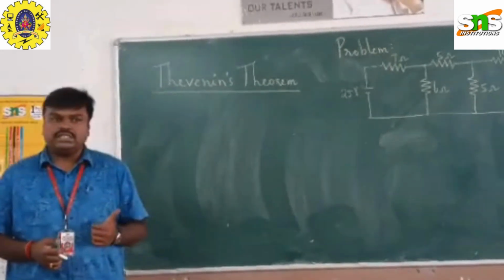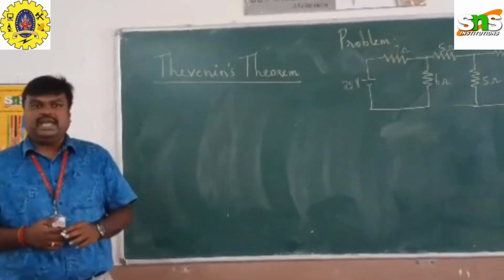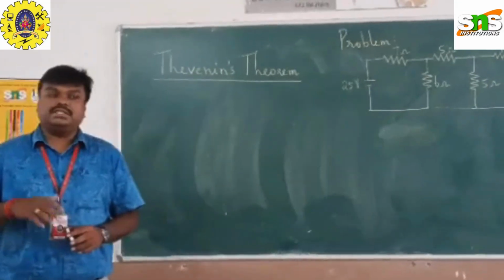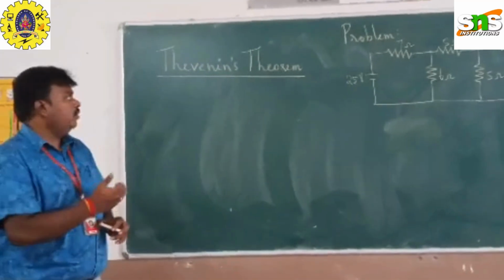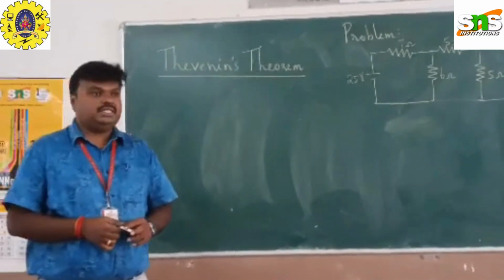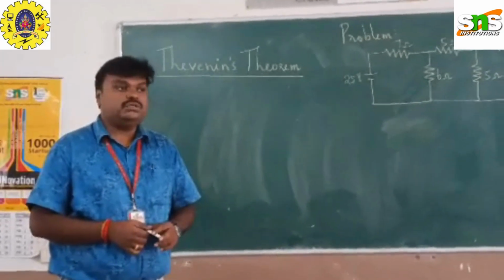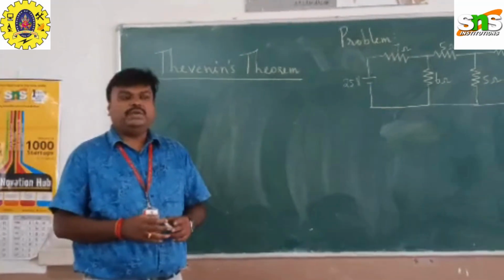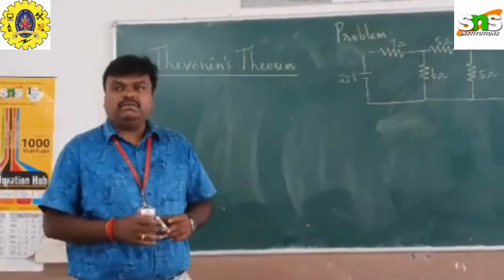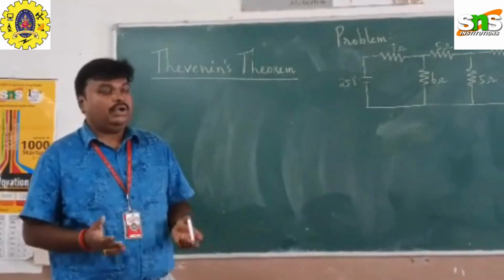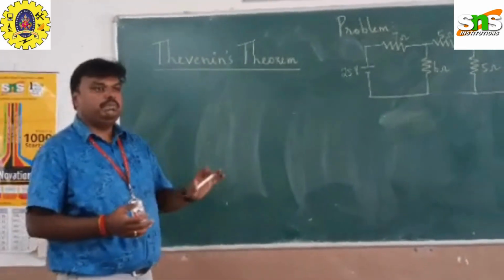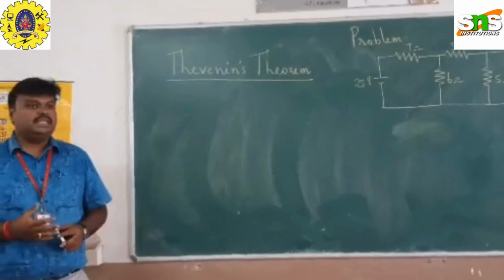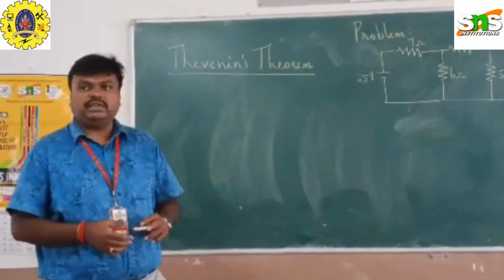The next theorem we are going to see is a very important concept as far as our circuits are concerned. It has major applications in power system networks also. The theorem we are going to see today is called Thevenin's theorem. Thevenin's theorem gives the value of voltage and the resistance to be calculated, and we can convert any complex network into a simple network consisting of a single voltage source in series with a single resistance. That is Thevenin's theorem.